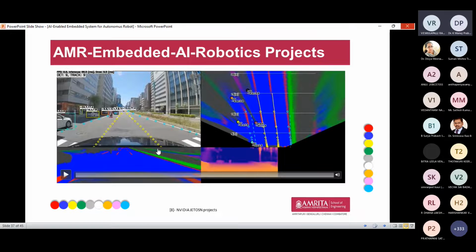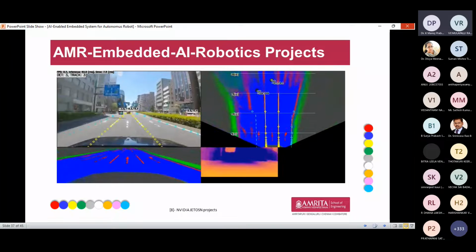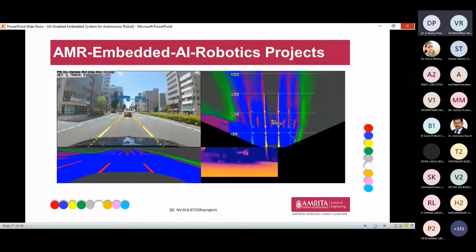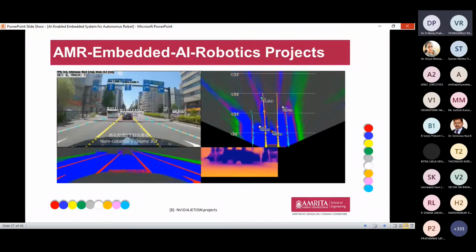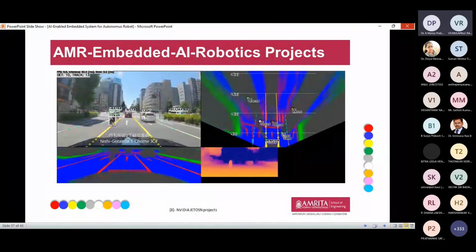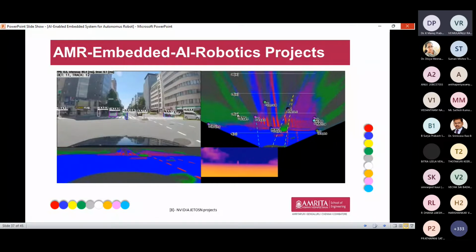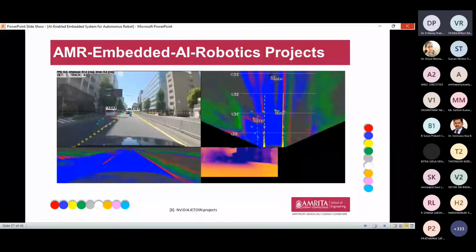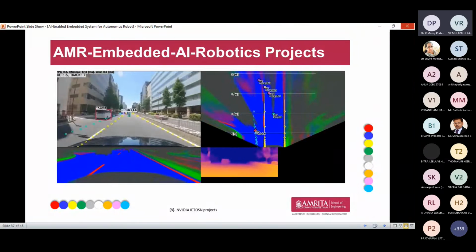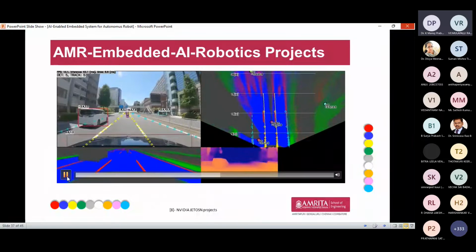It is not only used for mapping, but also in autonomous vehicles. Here deep learning techniques can be implemented, such as Mask R-CNN or YOLO techniques. A ResNet-50 technique can be implemented on this Jetson Nano. It can detect cars, do path planning, identify what type of vehicles they are and their coordinates. It also tracks and detects the vehicles in the road lane. On the right-hand side you can see the heat map. This is another example implemented on Jetson Nano.